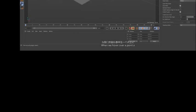When we hover over a point, a face, or polygon, they are highlighted and the corresponding icon appears. If the point is highlighted, we can move it by pressing the left mouse button. We can do the same with faces and polygons. By selecting a polygon and pressing Ctrl, the tool allows you to make extrusions. If you do the same with a face, a new face is created, and we can do the same with points.